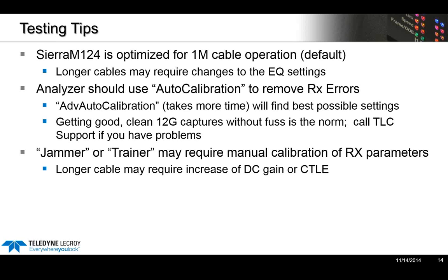We have the first one, it's just an auto-calibration button. You push the button, and chances are it will clean up the signal nicely for you. If that does not clean it up well, we have an advanced auto-calibration feature, which can take some time to complete, that should arrive at the very best possible eye.